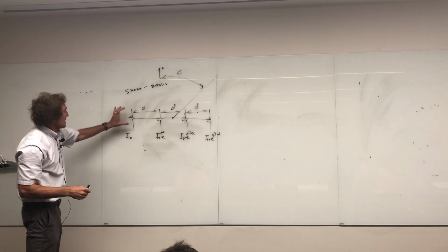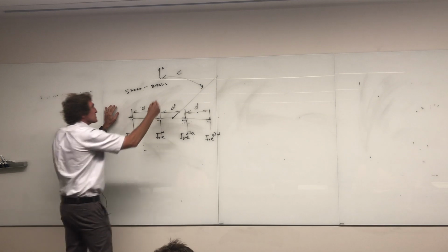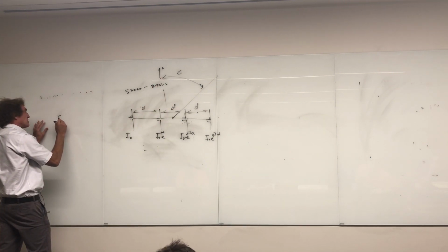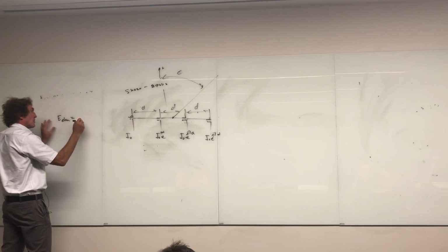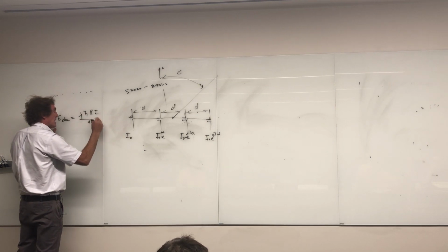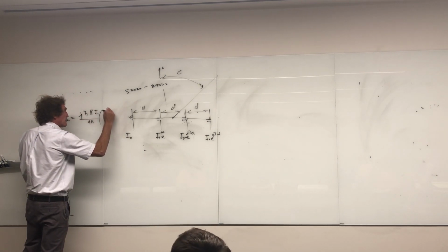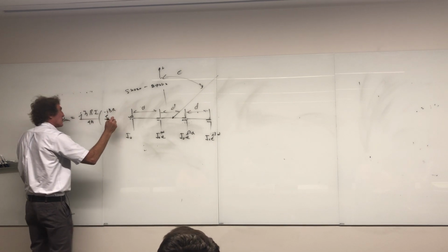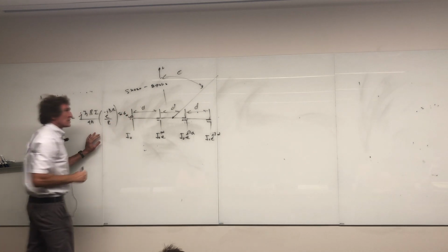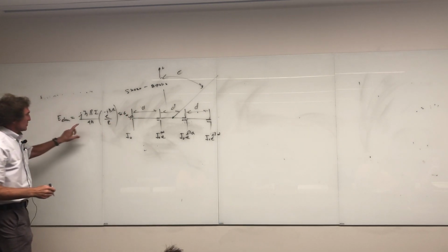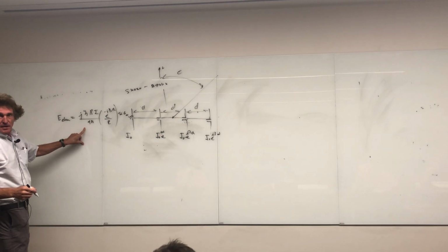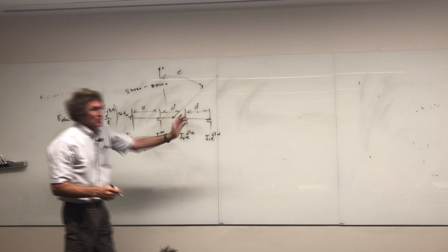Well, first for this one, if this is a short dipole and it's measured with respect to the z-axis by theta, then I can say the E field from a short dipole element would be j eta beta I over 4 pi times e to the minus j beta r over r, and then times the sine of theta, in the a theta direction. So from a single element, we know that's the field, right? Are you with me? For a short dipole, I'm going to say I've got 4 short dipoles with that progressive current.